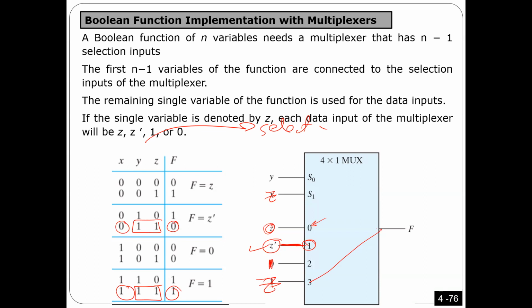So it's like the multiplexer was able to reduce the complexity of the function from 3 to only 1. Something outstanding, especially because the more inputs we have, the more complicated it is to design the circuit, because you have too many variables. So the way I did it here is, f became a function of only 1 variable, c, instead of three variables. You get what I'm saying?